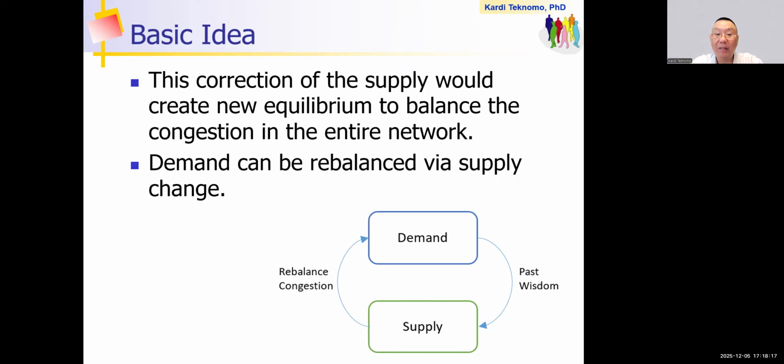So that's the basic idea of congestion redistribution. Our argument of congestion redistribution may not be accepted if we keep using average travel time or average network speed as the performance measure. Instead, we need to use maximum congestion as the performance criterion. Why? Because maximum congestion happens only in one or a few links. One often mistakenly thinks that it is a measure of a link. In fact, maximum congestion is a measure in the network, not in a link.